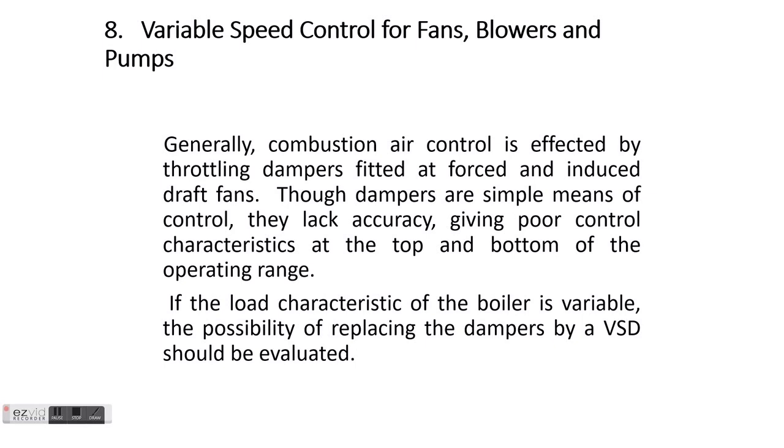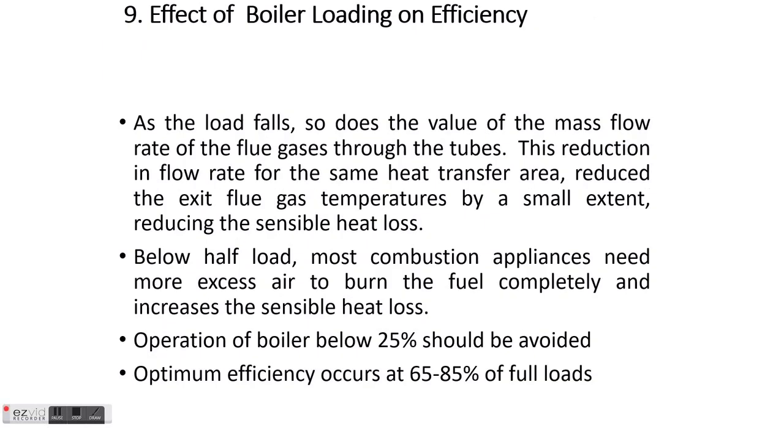8. Variable speed control for fans, blowers and pumps. Variable speed control is an important means of achieving energy savings. Generally, combustion air control is effected by throttling dampers fitted at forced and induced draft fans. Though dampers are simple means of control, they lack accuracy, giving poor control characteristics at the top and bottom of the operating range. In general, if the load characteristic of the boiler is variable, the possibility of replacing the dampers by a VSD should be evaluated.